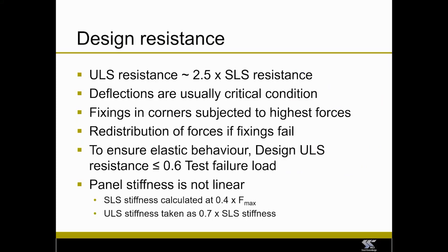Some general points about what you find when you do the testing. Firstly, the deflection case is the critical case for boarded walls. So you get a very high ultimate limit state resistance, typically 2.5 times the serviceability limit state resistance.